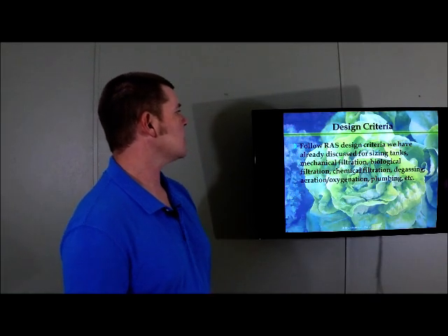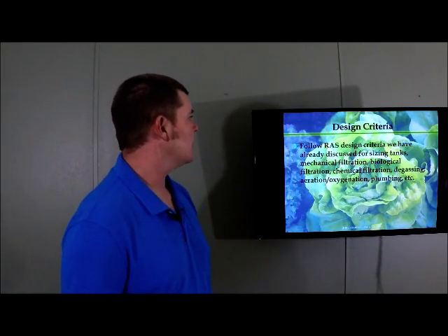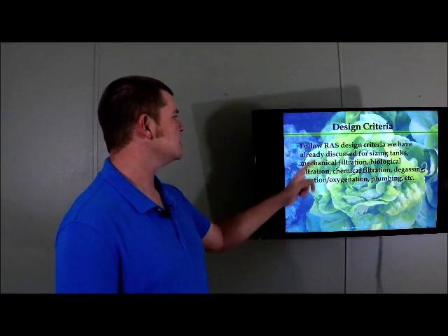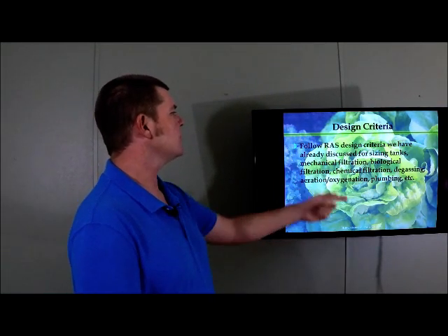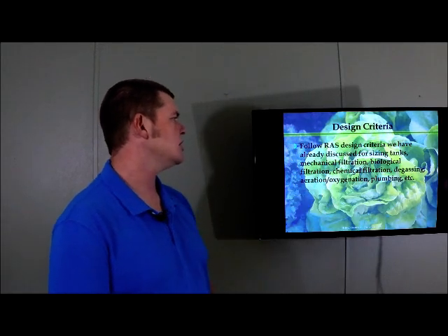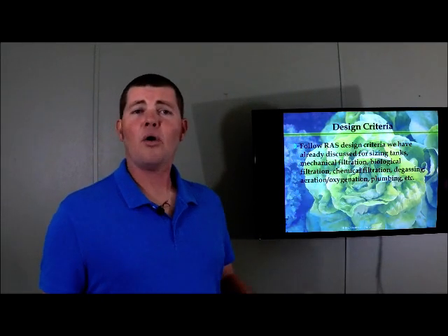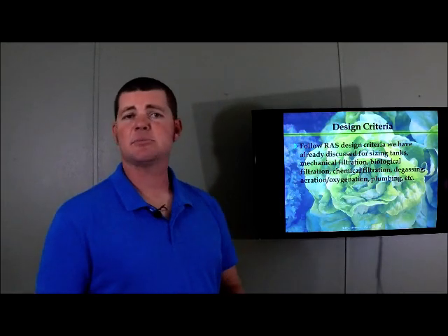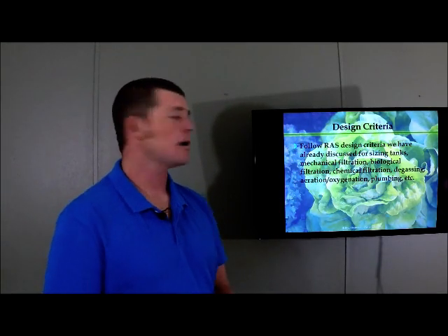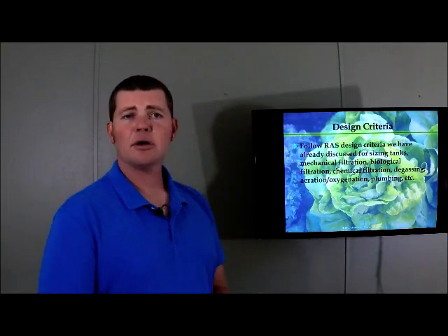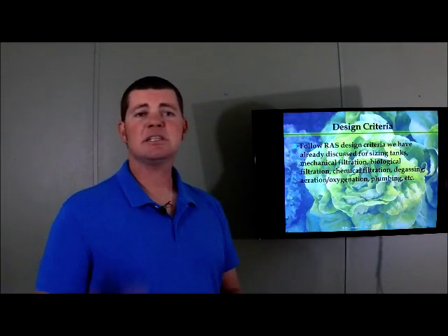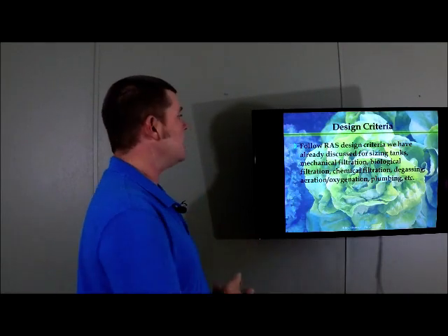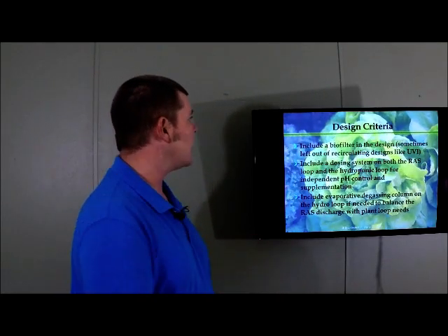Follow recirculating aquaculture system design criteria that we've already discussed for sizing the tanks: mechanical filtration, biological filtration, chemical filtration, degassing, aeration, oxygenation, plumbing, etc. We already know how to design this. You already know how to design this before I even go through this entire talk. So the recirculating aquaculture system, the fish side, you're going to design it just like we talked about in the first few sessions. That's done. No magic decoupled trick there.